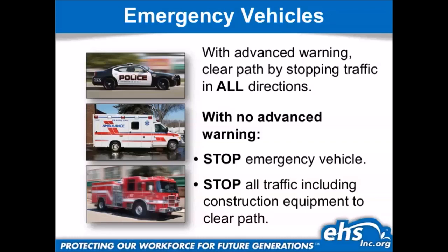With no advance warning: as you guys know, not every emergency vehicle has its lights and sirens going every time. Sometimes they'll be going back to their yard or the hospital, not dealing with an emergency, so they'll be traveling like anybody else. Let's say they have to respond to an emergency while they're stuck at your flagging station. Just because they kicked on the sirens doesn't mean it's safe for them to go through that flagging station.